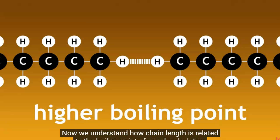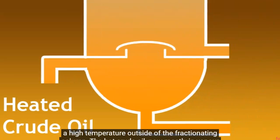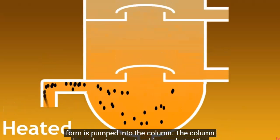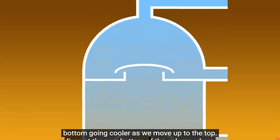Now we understand how chain length is related to the boiling point of a molecule. Let us look at how this method works. As you can see, crude oil is heated up to a high temperature outside of the fractionating column. The hot crude oil, now mostly in vapour form, is pumped into the column. The column has a heat gradient and is very hot at the bottom, going cooler as we move up to the top.